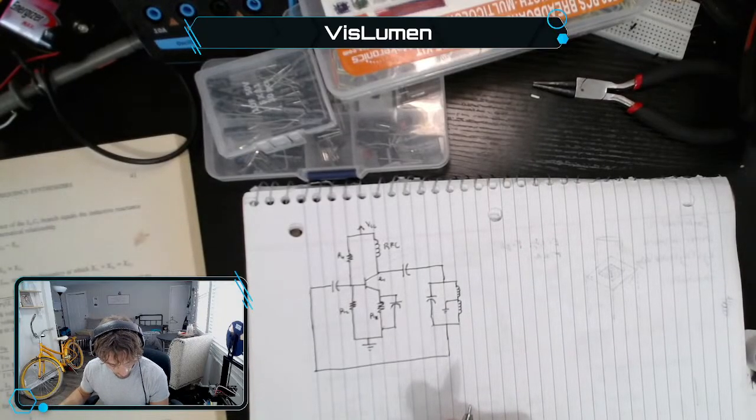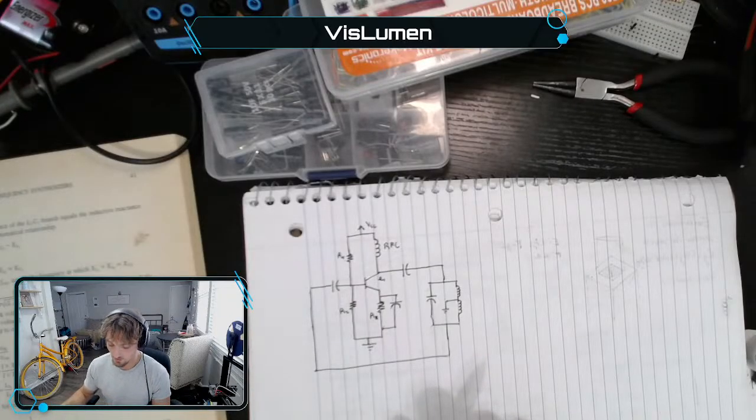Call it B, L2 or L1, B, this B. To satisfy the Barkhausen criterion for oscillation, the A_V B product must equal 1. Solving for A_V gives us... okay, very well. Therefore, the frequency of oscillation, F oscillation, equals the frequency at which XL1 plus XL2 equals XC3. Okay.